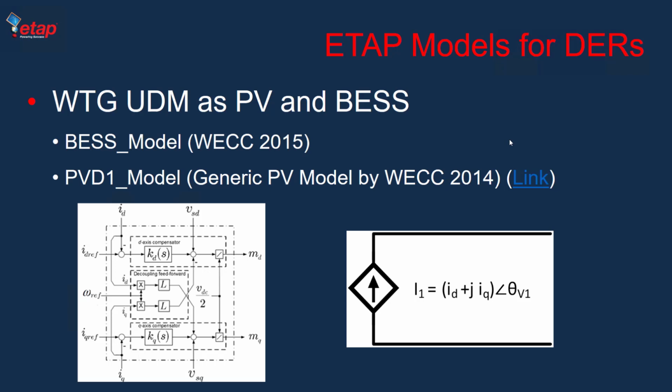In transient stability software, the control system defines the direct and quadrature components of the current that needs to be injected into the system, based typically on the voltage and power measured at the terminal of the DER.